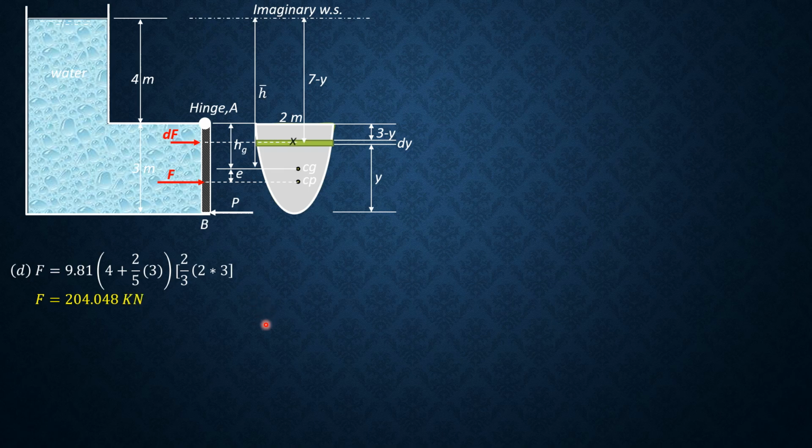Next, for E, it is equal to I sub CG over area barred H. So assuming we do not know the moment of inertia of a parabola, let's derive it now. So Ix, imagine that the x-axis is a horizontal line through the vertex.